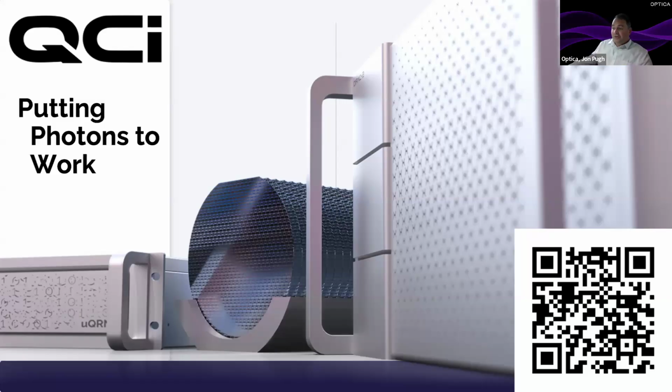And you mentioned that you use your fast e-beam for the writing. What is the resolution you offer with this e-beam? And also, do you offer any DUV lithography? We're working with partners for DUV lithography. We don't own a stepper ourselves. The resolution, you can easily go down to 50 nanometer resolution with this tool without any tricks. And with tricks, you can probably push it to 25, but that's not something that's necessary for this type of work.